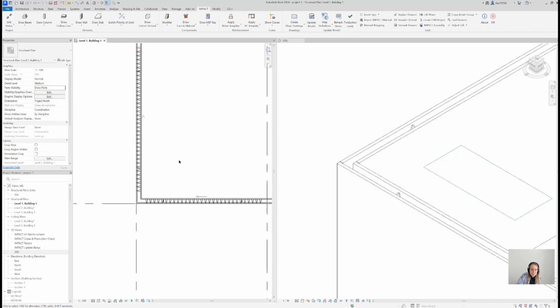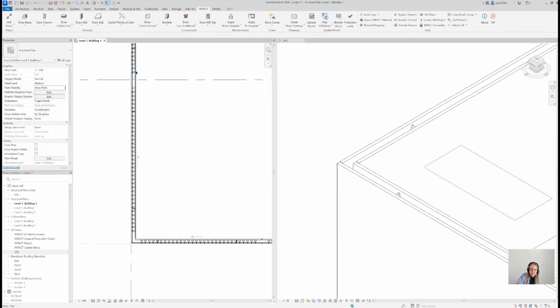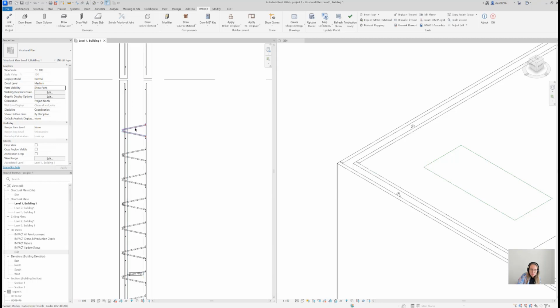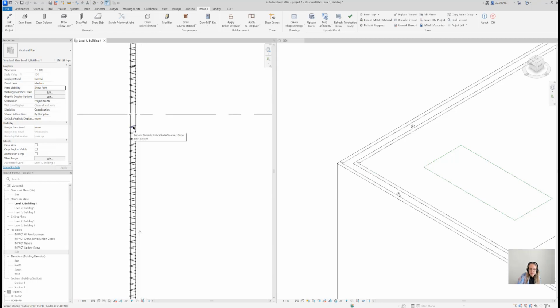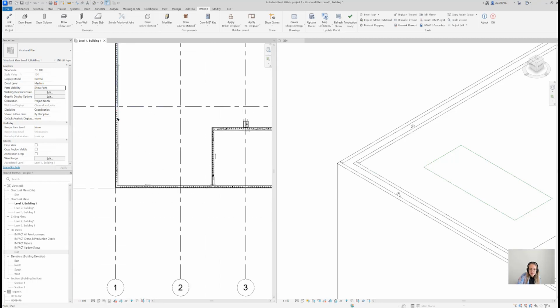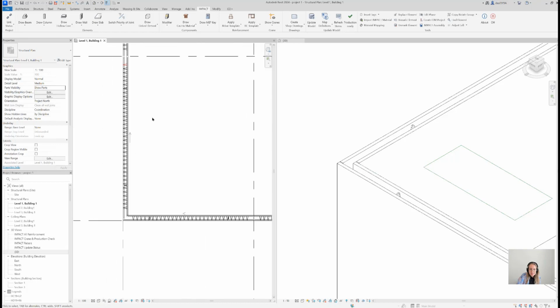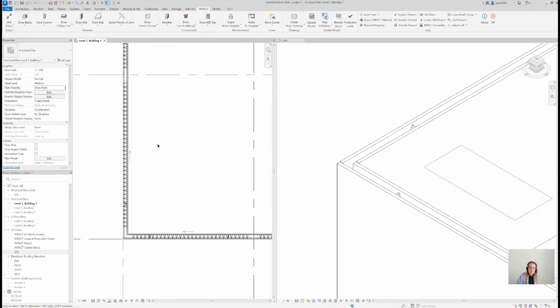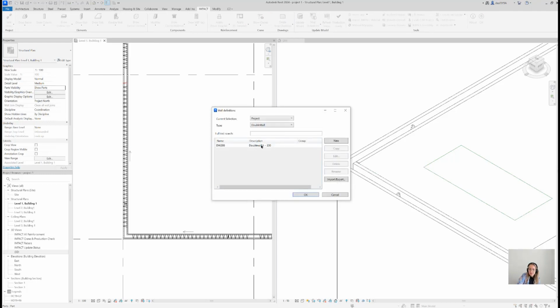I think we're there where we can solve the mystery of why some lattice girders on the edges are colored in red. And this is primarily because of your settings in the definition. Everything that is drawn by Impact takes reference in the definition of the element.